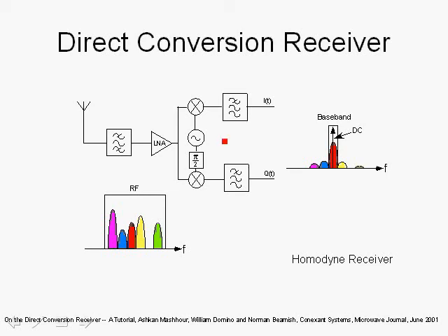In a direct conversion receiver, one issue that will arise is IQ mismatch or IQ imbalance, and that occurs for a number of reasons. One is the fact that you have unequal gains on the in-phase channel receive chain and the quadrature phase channel receive chain, so you might have imbalance in the gains. In the synthesizer shown here, you can have a gain mismatch between the in-phase component, the cosine of 2 pi fc t, and the sine of 2 pi fc t over here. You can have a gain mismatch.